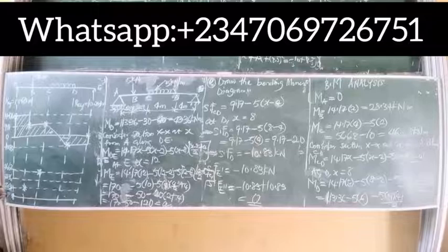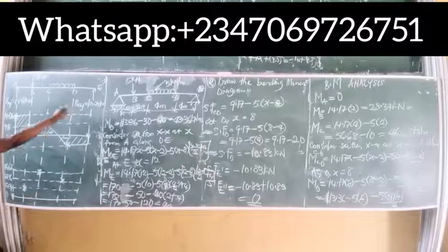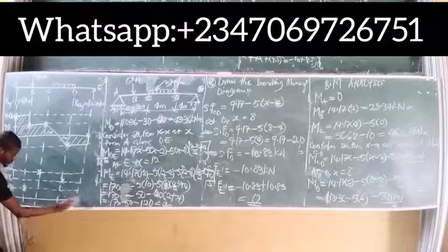Look at the point on the beam where the shear force changes sign from positive to negative. That particular sign becomes the shear force equation that we're going to present to them. Is that okay? Okay, give me the moment at D. 43 points. This is line D. This is 43 points. This is where they meet. And of course, moment at E is 0. So you simply have it.